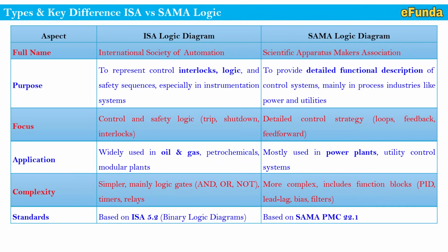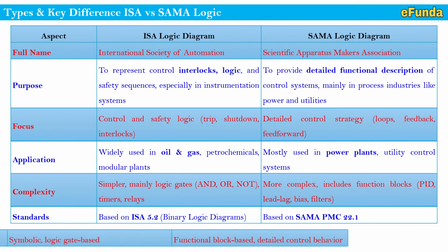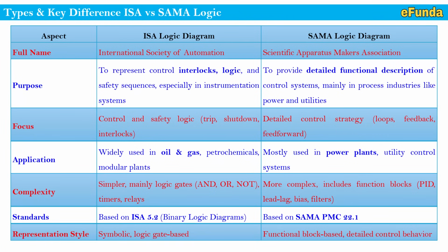Applicable standards: ISA is based on the ISA 5.2 binary logic diagram, whereas SAMA logic is based on the SAMA PMC 22.1 standard. Representation style: ISA logic is symbolic, logic gate based, whereas SAMA logic is functional block based. Detailed control behavior type style representation is being used.